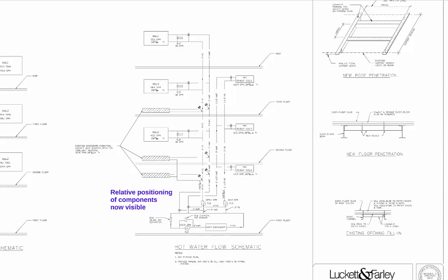Just because we showed you that the air separator is best to be placed on the suction side of the pump does not mean that every hydronic system out there exhibits this practice. The engineer may have good reason to put it elsewhere, or maybe he just hasn't taken such a sweet class like this.